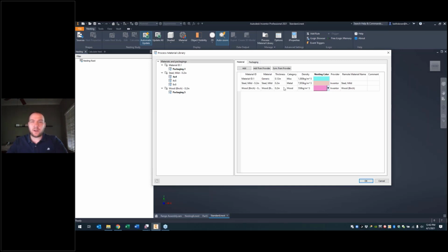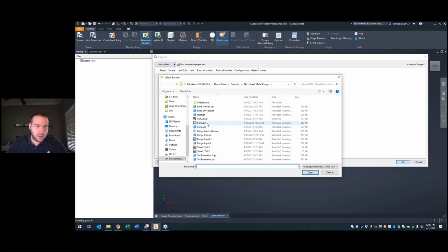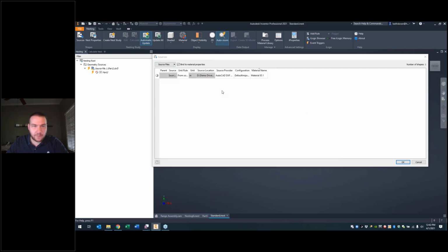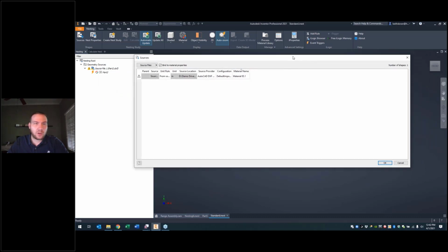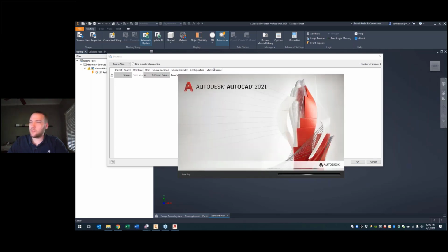from an existing object. Now, another question that just came in was, can I pull in DXFs and work with them? Yeah, if I go to sources here and I go source out a specific part file, it'll bring that in, but it doesn't know how thick that material is. The other thing that does matter with that profile shape is it does have to be a closed loop. I just grabbed part 2. Let me go look at that real fast and make sure the part 2 DXF isn't broken. It should have been a closed profile, but I'm not 100% certain.